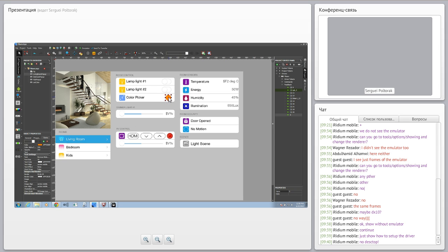With this item, the circle here, we want to show the color of our LED driver. For this, we drop RGB_5 because we want the color. We drop it on the UI element, and instead of selecting value, we want to select more, and here we want to change the color of the device, not its state, but the color.